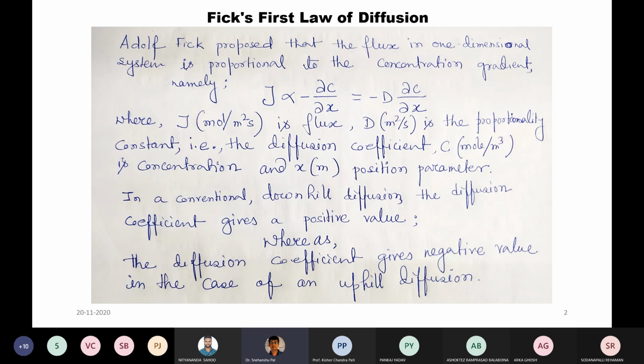So if you are annealing such an inhomogeneous single phase alloy, what will happen at high temperature? The matter will flow in such a manner that, with time, it will decrease the concentration gradients. If the specimen is annealed long enough, meaning the annealing time is very long, then it will become homogeneous, and the net flow of the matter will slowly cease. It will stop.